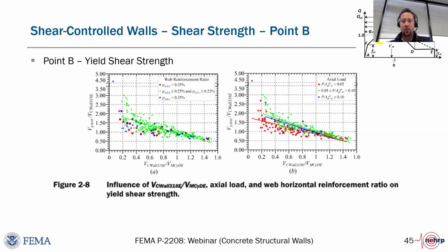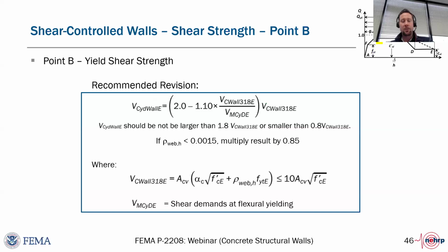I guess it really benefits to have a flange there on the cracking strength. So yield strength, you can see a pretty good correlation in the trends there on the tested strength versus the recommended strength coming out of these technical recommendations. And this was interesting. What we found is that when you calculate ACI 318 shear strength equations, you actually did pretty well when the wall was close to being on the borderline between shear controlled and flexure controlled.